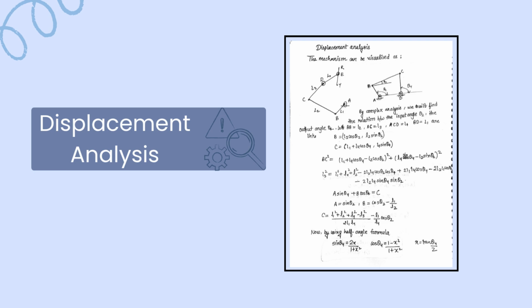By representing the linkage geometry mathematically and assigning one joint as the origin, we found the coordinates of other joints and calculated the output angle, that is theta 4, corresponding to each input angle, that is theta 2. For our setup, the linkage connected to the wiper was 30 cm long and the coupler linkage length was 50 cm, divided as 7.5 cm on each side.